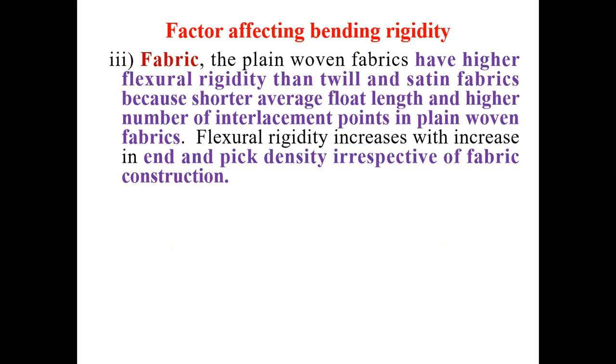So there are two important things as far as the fabric is concerned. First of all, what is the construction of the fabric? Is it a plain weave or twill or satin weave? If the number of interlacements is more, then the fabric will be stiffer. And also if you go on increasing the number of yarns either in the warp or in the weft direction, then also the fabric will become stiffer.